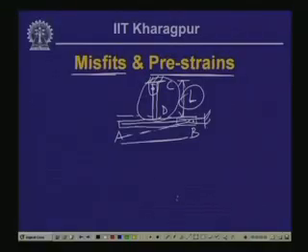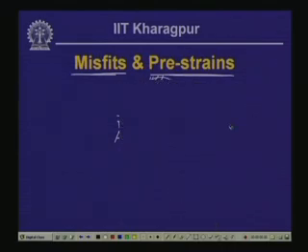On the contrary, if we look for a structural system which is indeterminate, and we have any member which is shorter or longer than its actual length, then that induces strains or stresses in the system. So, if we consider an example where the system is an indeterminate one, let's look into that. Say we have again a bar